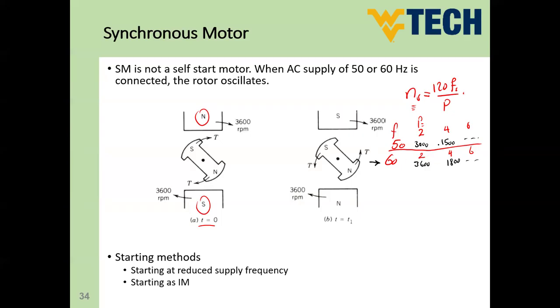And the same is true for a 50 hertz machine. If the supply is 50 hertz, you don't have a synchronous speed between 3000 and 1500 RPM. It's impossible. So for that, guys, synchronous speeds are some definite numbers. It cannot be any variable speed. It can only be variable if you make the frequency variable, and this is possible if you have a variable speed drive, which changes the supply frequency. So you can have whatever frequency you need in order to do speed control with different values.